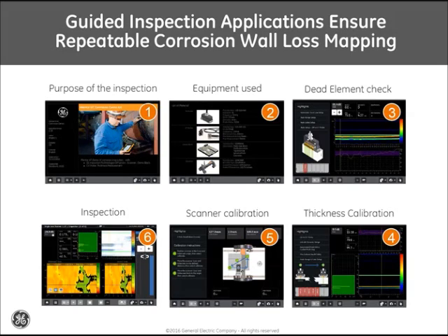By following through and completing those step by step, you arrive at the final step, step number 6, where the inspector would be all prepared to do a rapid and simple scan of the suspect area, where he would have the C-scan image as shown on the bottom, which indicates the remaining wall thickness of the component, and some other information on the top of that display, which the inspector will use to help ensure he is inspecting consistently.